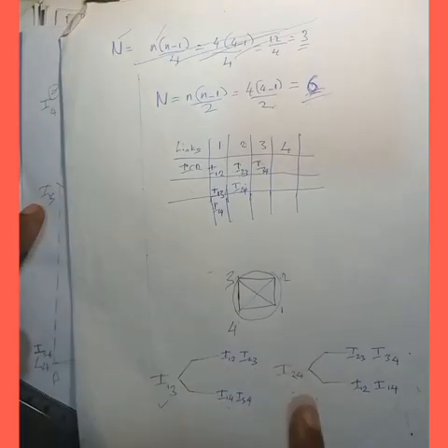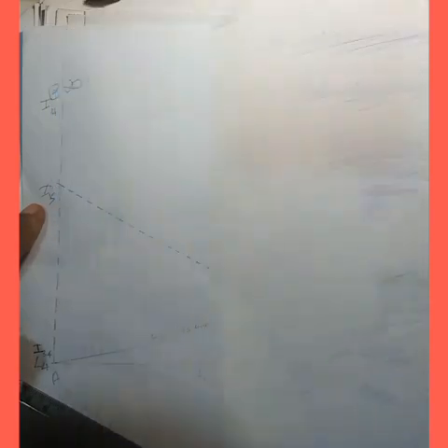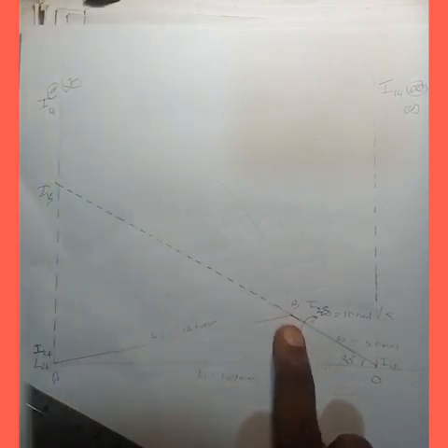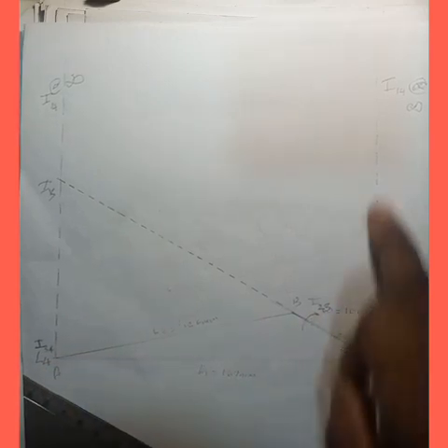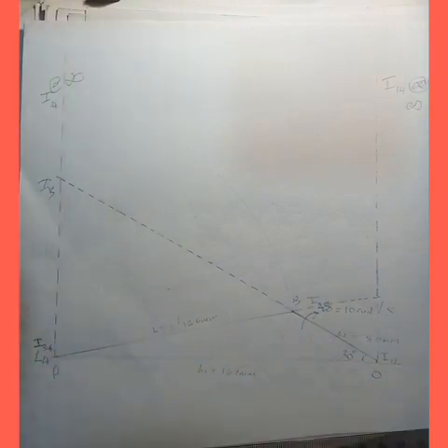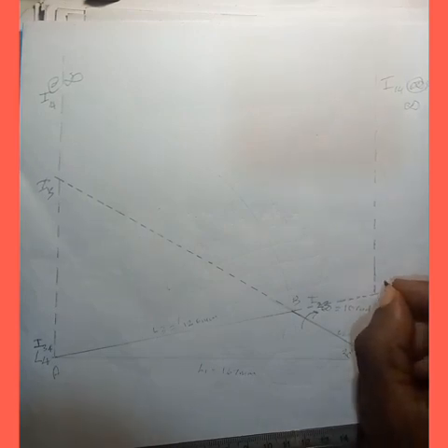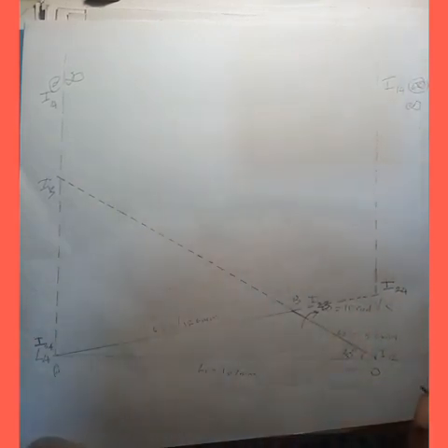So the next one is now I24. For I24, this goes this way. It goes from I23 and then I34. So it means you're going to draw this line to intersect this vertical line at I24. So you can see this is the short dash line, and then this is the point of intersection, I24. So now we've been able to locate all the instantaneous centers.